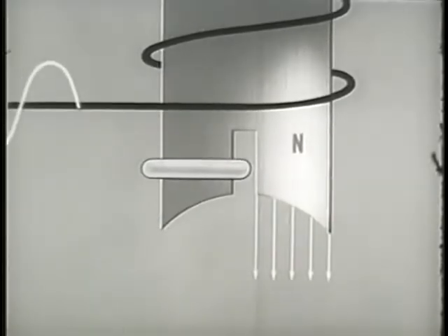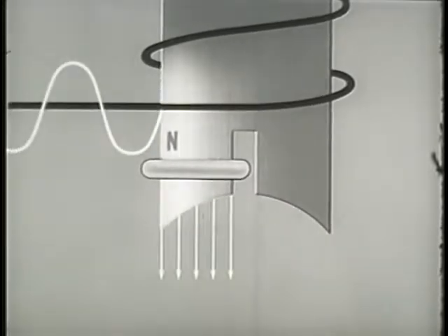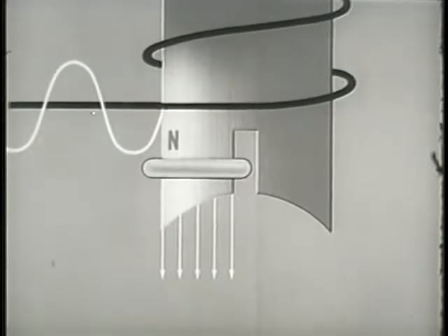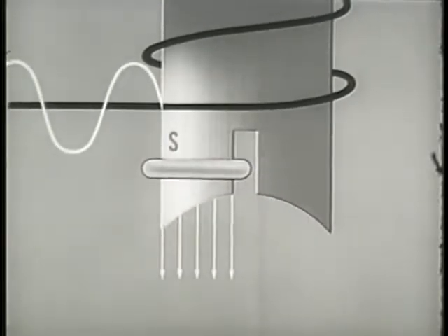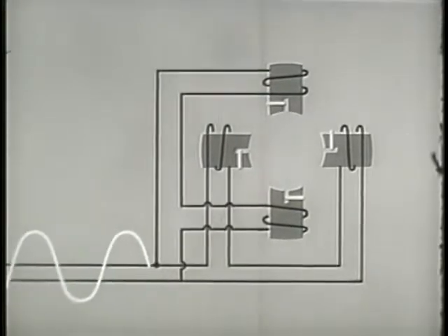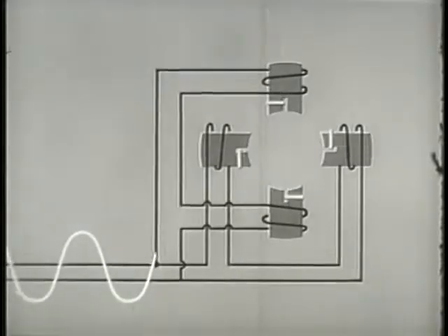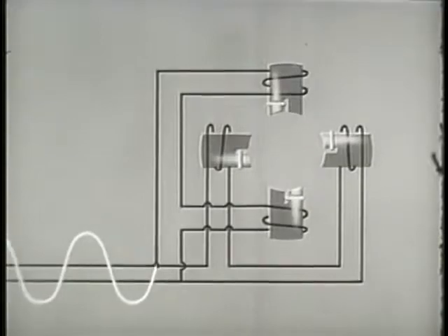Lines of force will emerge from this unshaded section of the pole face first. The inductance caused by the ring makes the shaded portion of the pole lag behind. This alternating pulsating action creates a phase difference within the pole. Let us see now how the use of shaded poles actually produces a torque or turning force in a single-phase induction motor. The single-phase AC energizes the unshaded portions of the poles first and creates magnetic fields in these areas.